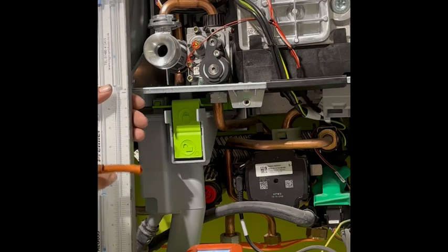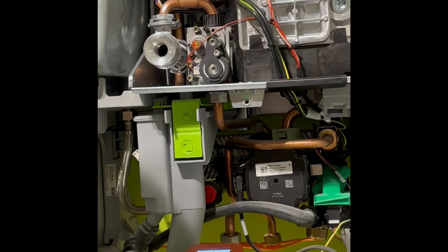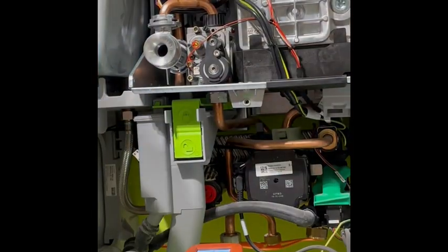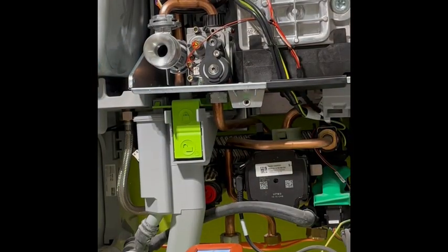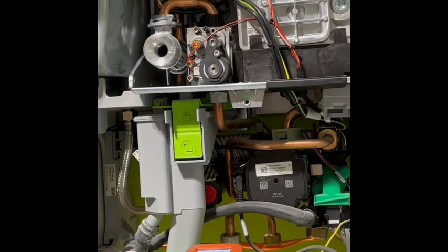If they're struggling to open, so it's a gradual opening of the gas valve, sometimes that can suggest a fault as well. So first and foremost, when you turn up on your ignition fault, try and fire the boiler. It's important to see at what point of ignition the boiler fails at. So that's all we're looking at in an ignition fault, we're trying to work through the process. The fan's going to run first to purge the heat exchanger.